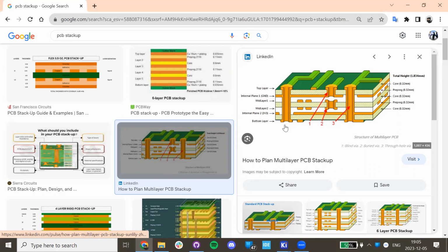And another thing that exists is these holes called vias. As you can see here, what you do is you drill a hole through the PCB and you fill it with copper. I don't know if that's the exact process. I think they probably do something a little bit different, but it's basically a copper filled hole so that current can go from one layer onto another, or not at all onto that layer, as you can see here. So that is just a way for us to connect to another layer.